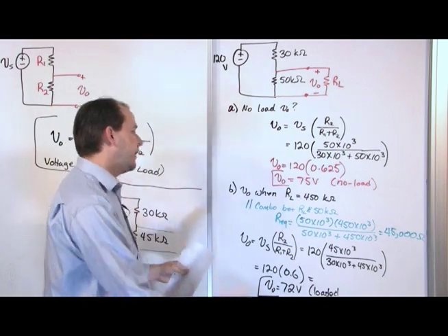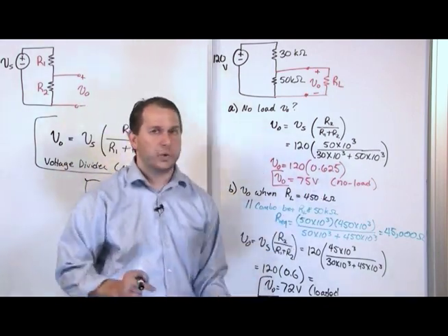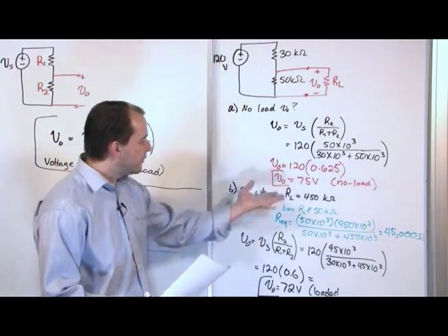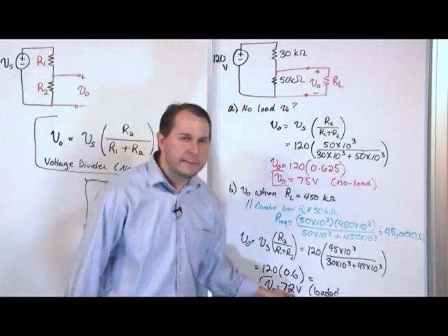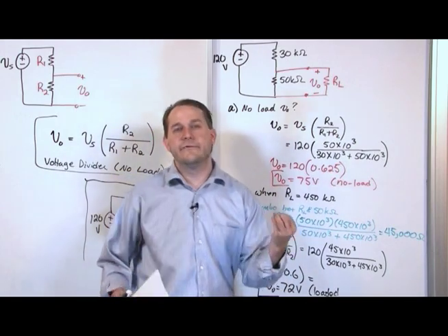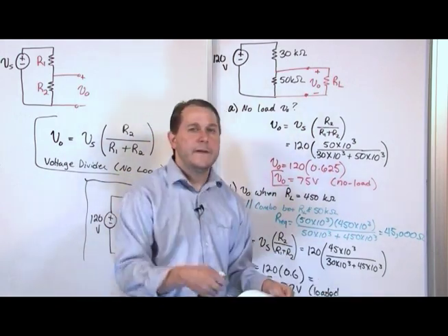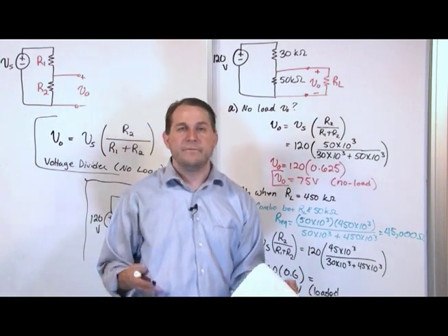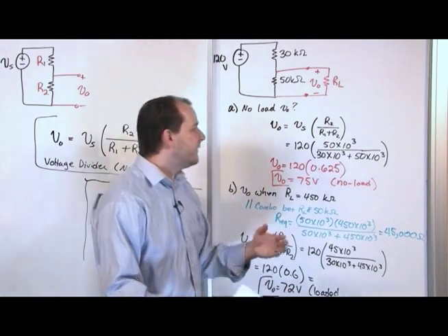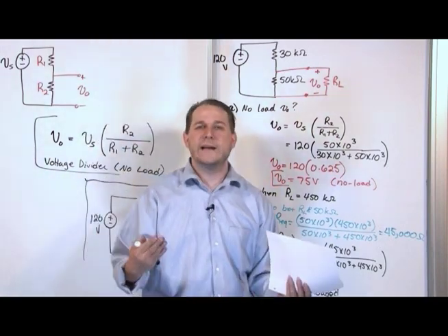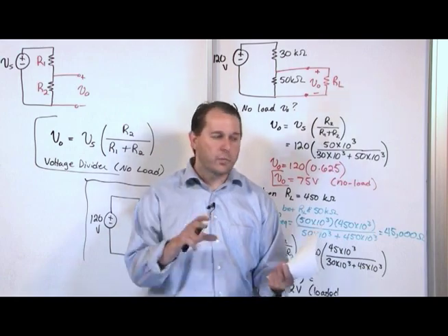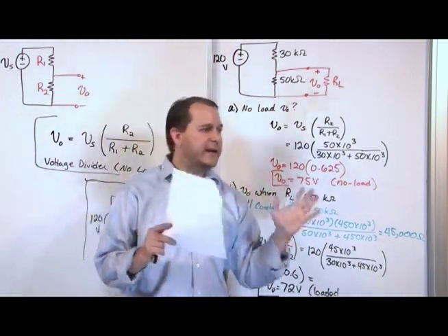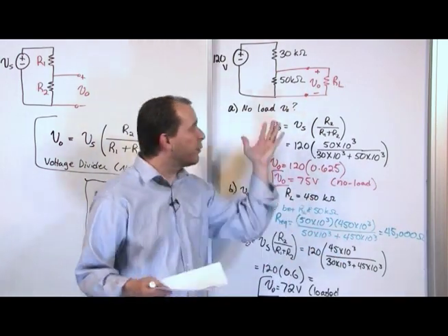If you go the other direction, like we said a minute ago, if you make this a million ohms, or 10 million ohms, or internal resistance of 25 million ohms, and you do all these calculations again, you're going to get something extremely close to 75 volts. So most voltmeters, when you hook them up to a circuit and measure, have an internal resistance very typically in the millions of ohms. Very, very high resistances, so as to not alter the circuit, because ultimately you don't want any current flowing in that voltmeter. You just want a pure voltage there. So there are other considerations, depending on what you're trying to do in your circuit.